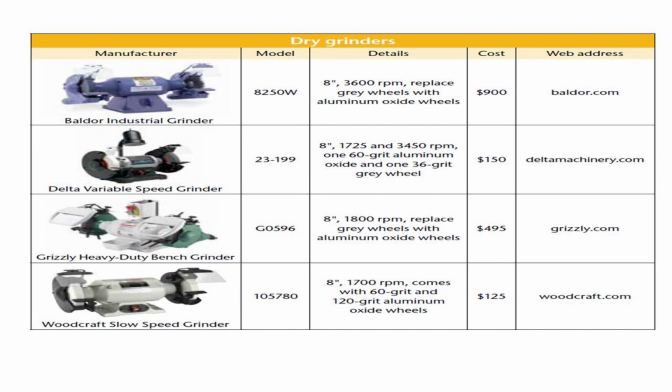When you get down to it, there's basically dry grinding and wet grinding. In dry grinding, you've got the wheel, you've got the belt, like a belt sander, and then you have others that are a horizontal flat disc that you can grind on. This is out of the AAW, where they looked at the variety of manufacturers, the size, and the speed. You'll note that most of them are generally 1,750 to 1,800 RPM. Some others turn at a higher speed, and as you go to higher speed, you're going to generate more heat. And price, whatever you want to pay, you can find.